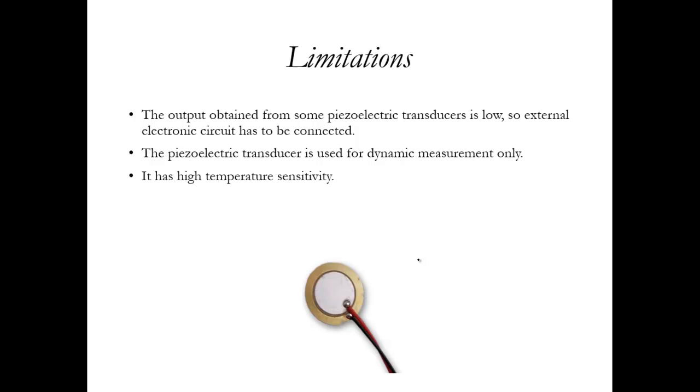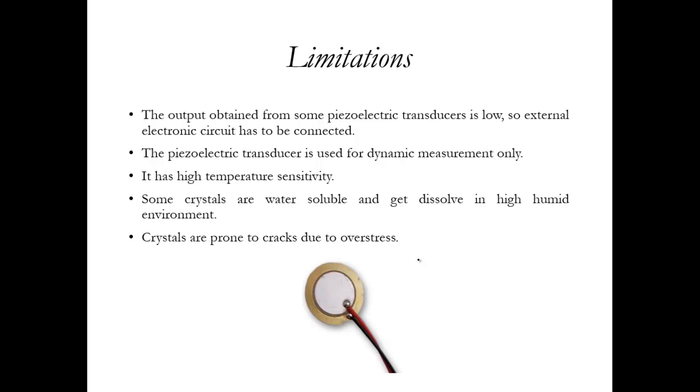And it has high temperature sensitivity, so as the temperature increases or decreases, or in other harsh conditions, this may have a different kind of impact on the performance of the instrument. That is very important to be considered. And some crystals are water soluble. They get dissolved in high humid environments, and they are also prone to cracks due to overstress, because we're using them as sensors, and if there's an overstress, these crystals may crack.